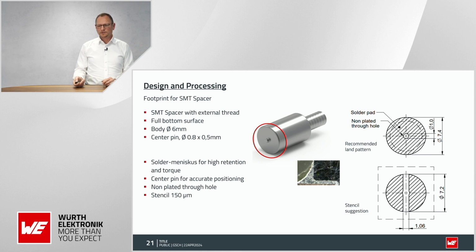So that's why you need a stencil here, like on the right side. You have the pattern filled here, which is the one that needs to be soldered, and you should make sure that no solder paste goes inside the through hole here.